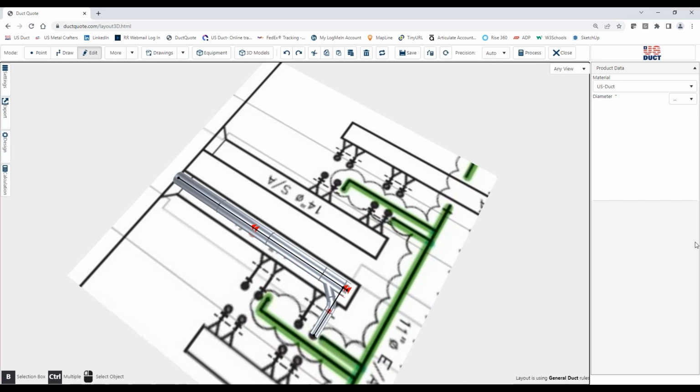Now, it may be that their connection points require a flange to be connected to, and that's a good reason. You might expect then that you're going to have to put a flange adapter on the end, or you might be using all flange duct. And again, typically you can in fact use those hard connections to those pickup points as long as the proper amount of space is allowed to get all the fittings into place.